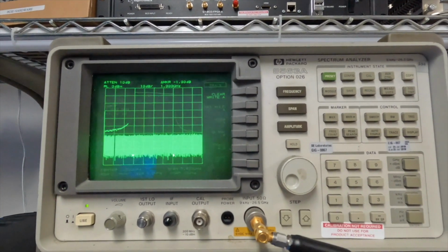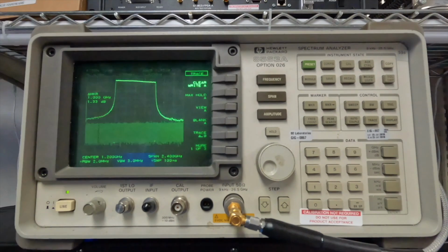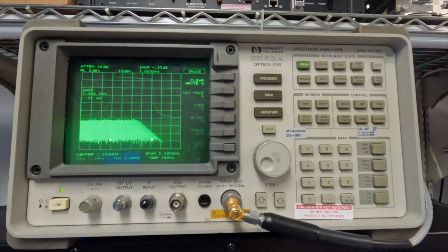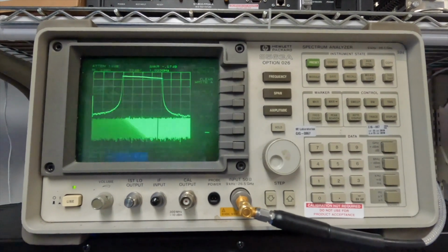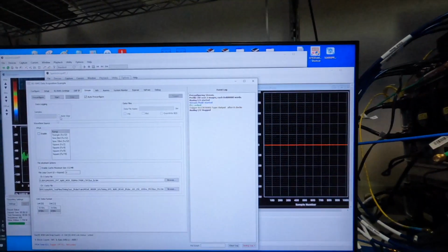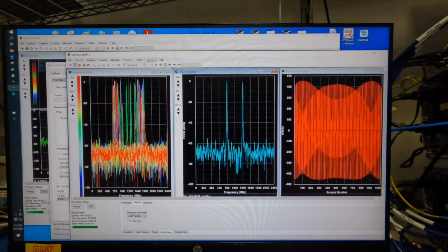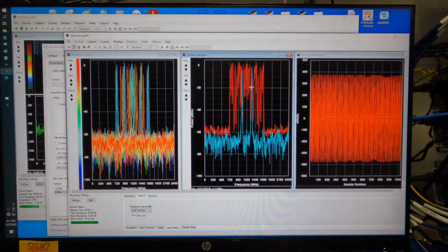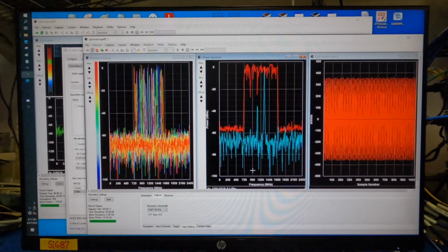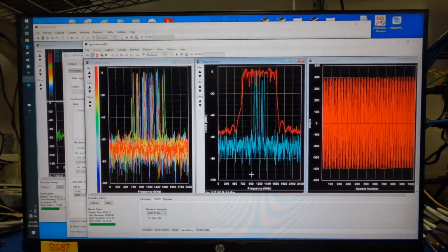Okay, so I've taken the RF playback of the 1 gigahertz chirp centered around 1.2 gigahertz, and I'm going to put it into the second of the A to D channels in the CEDAR capture workstation. So no signal in. I'm going to start the playback. And here is our 1 gigahertz chirp centered around 1200 megahertz on the second A to D channel.